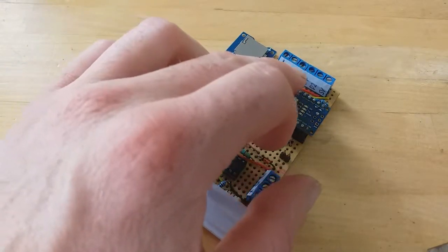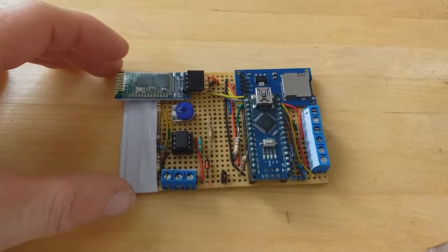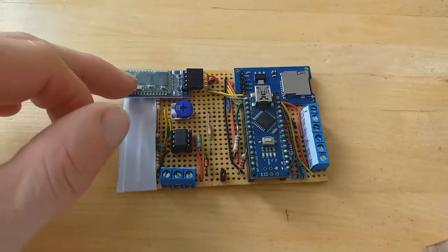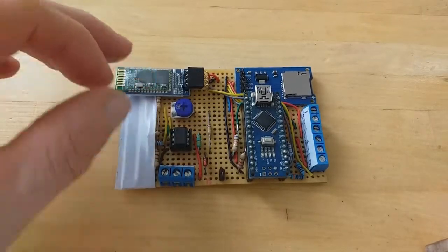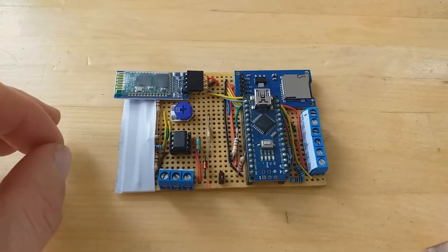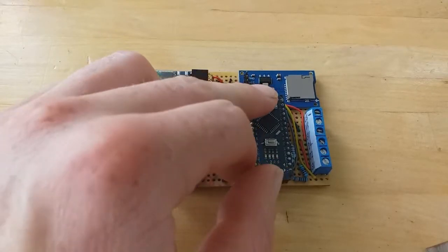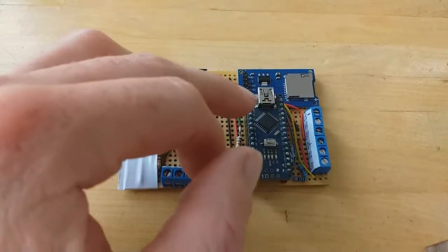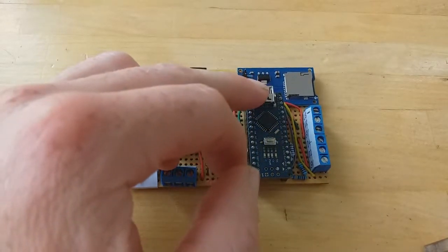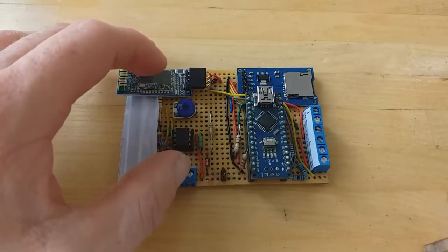I've also got an extra 5-volt connector there, so I don't have to shove two wires into one connector for the two reed switches. And because I've moved that connector block from there, I've actually had space to add a Bluetooth module. Now that makes it a lot easier just to check that it's logging properly, rather than trying to get a USB cable into here whilst it's in a little box. So also it's not really a good idea when you've got the V-in powered to also connect up the USB. They seem to be okay, but I don't like doing it much.